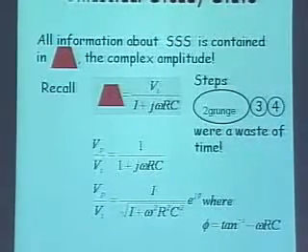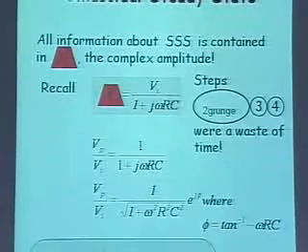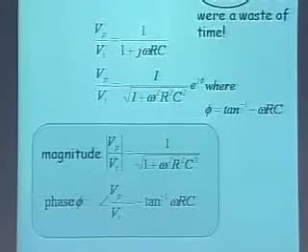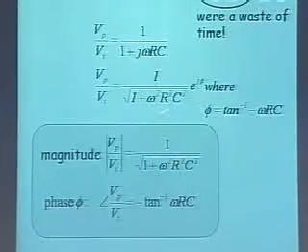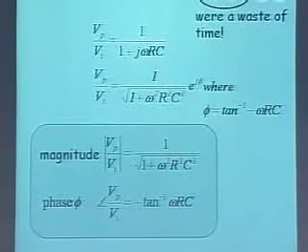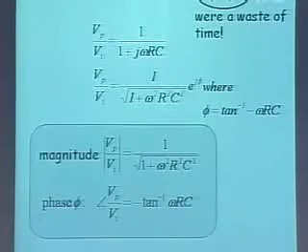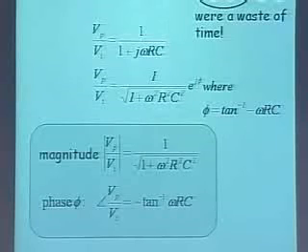And from VP, I can then compute the multiplier for the cosine as follows. I divide by VP here. Remember, the cosine was multiplied by, in the mathematical step that I did, VI divided by 1 plus this stuff here. So I can get the magnitude and phase of the transfer function of the circuit in the following manner.